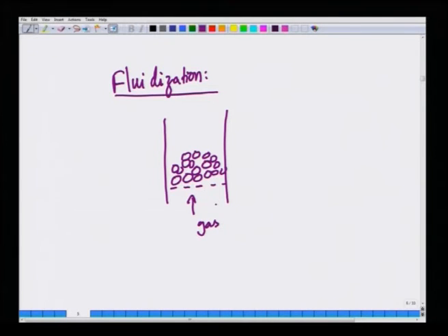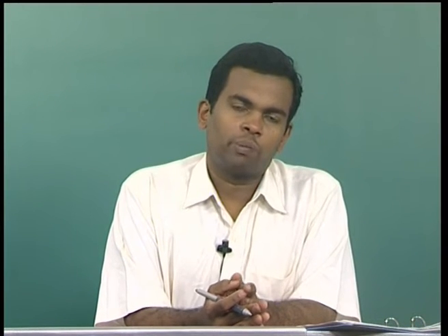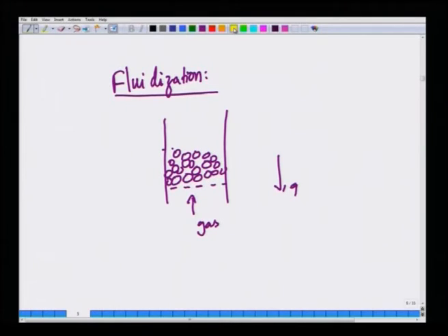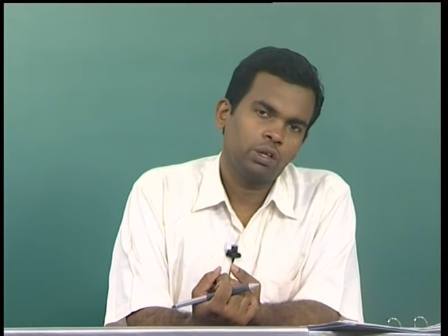Okay. So, initially it is a packed bed, but what is happening is initially the weight of the particles acts downwards, the gravity is acting downwards, and is now balanced by the pressure drop. The pressure drop that you exert to make the fluid flow is essentially balanced by the weight of the particle. If you do a macroscopic momentum balance, that is what will show up. If you take this entire thing as control volume, and if you neglect wall friction, the main dominating forces are essentially the pressure drop that you apply and the body force that acts on the entire bed, which is essentially due to the weight of the particles that are present in the bed.